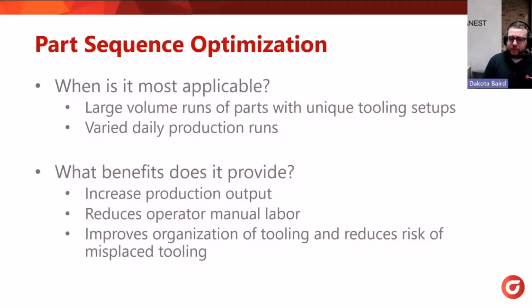The first question I've got here says, can we see the drawing of the program for mixed parts? I assume that's for the batch run process at the end. If by drawings you mean flat patterns, that automation tool is doing the whole programming process. You'd set it up to import the part, generate the flat pattern, create the press brake program, and also generate the bending report for the part as well. So you'd get all 3 of those files: the flat pattern, the bend report, and the NC for the machine. Hopefully that answers that question. If not, if you can elaborate a bit more, I can try and answer it a bit better.